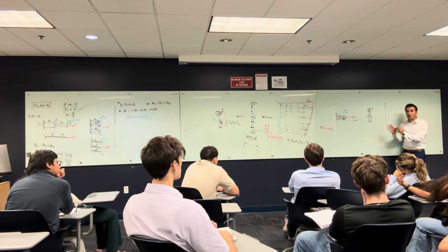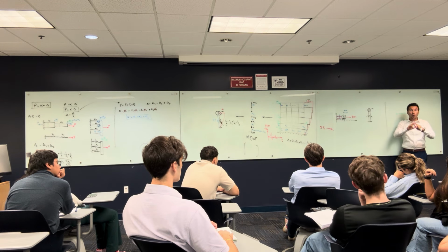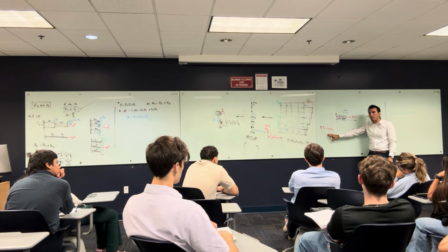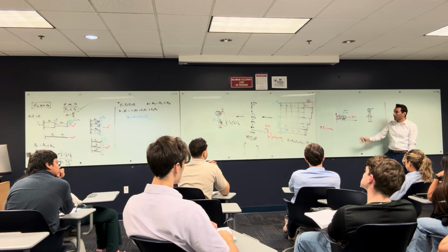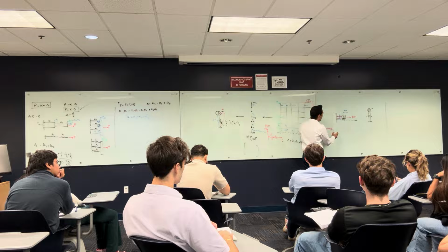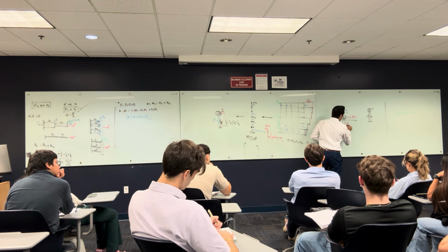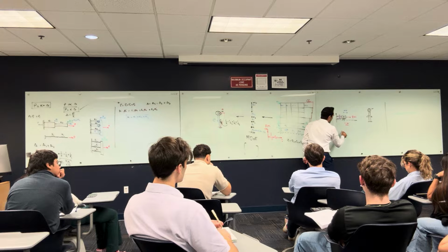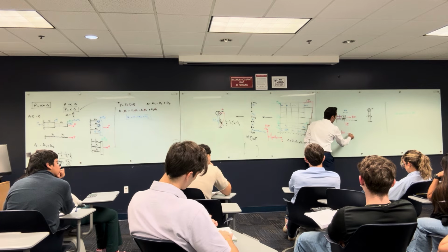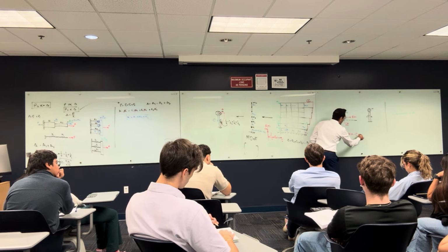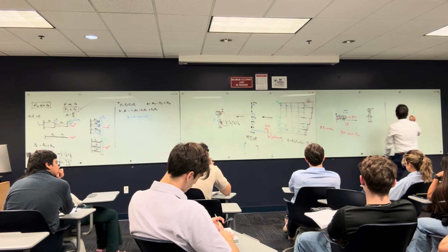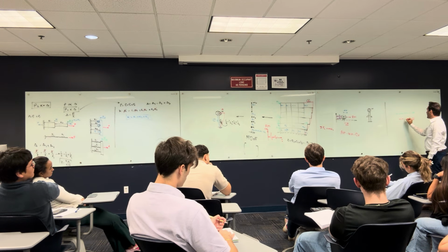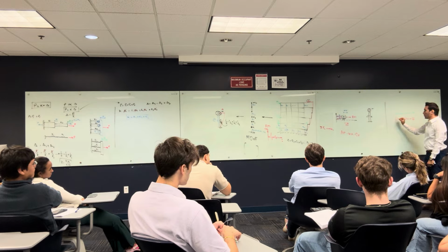So the force is equal to the mass multiplied by the acceleration. All the external forces applied to your body is equal to the mass of the body multiplied by the acceleration of the body. So what are the forces applying on this body? I'm gonna assume that the positive direction is that way, which is the direction of the motion. So I have my forces, Ft is positive, minus K multiplied by U, minus C multiplied by V. By the way, I said that we are gonna use U rather than delta, and I can say that V is equal to U dot and A is equal to U double dot, right?